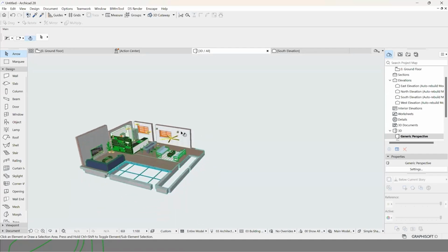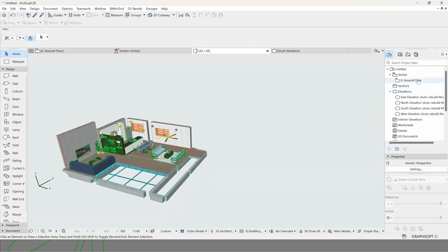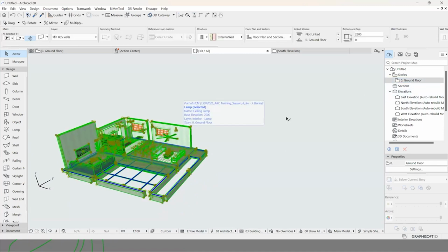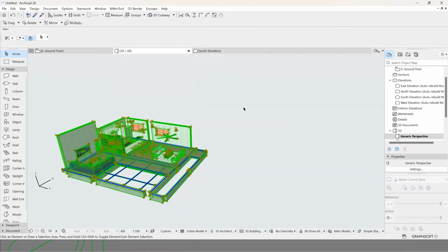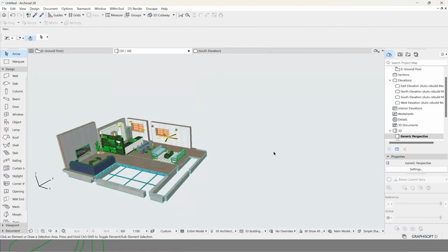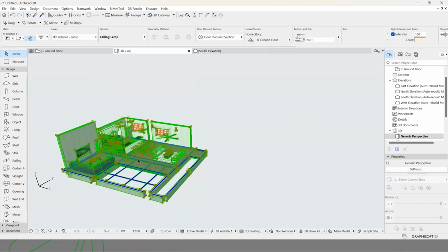But I hope you understood the concept. Make sure the layers are matching, like you mentioned, the levels. The same naming would be ideal, but if you have different types, then you can work accordingly. So in the host project, make sure you have the matching ones and then add it. One of the methods that we usually follow when it comes to the hotlink is that we use it for the typical floor and then replicate across. So these are some of the methods.